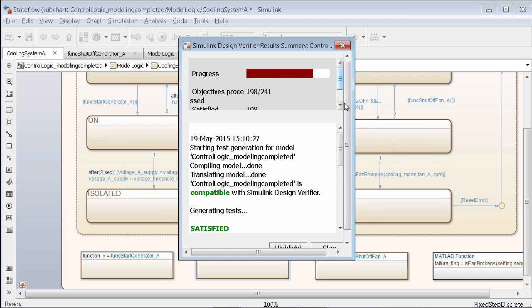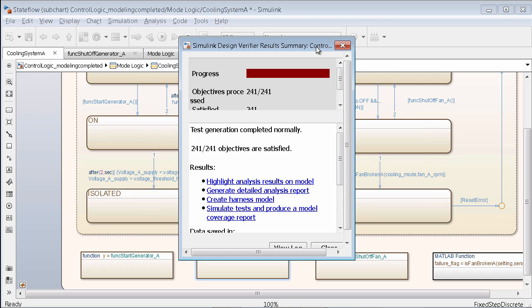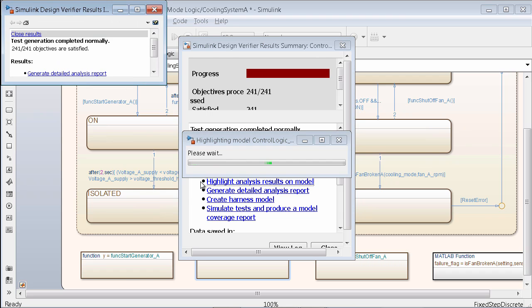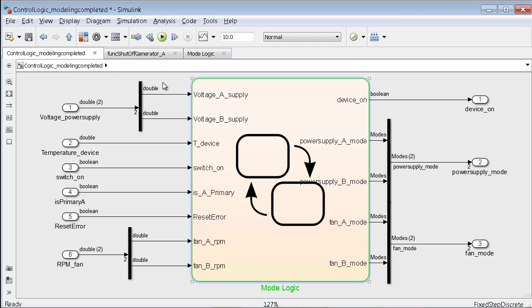Okay. So just to recap, at this point we're not in simulation. Right now, we're using mathematical methods to generate test cases to top off, as you said earlier, the test cases that we had functionally created. Now a user would probably go back and reuse these test cases in simulation and see how it behaves. And if you change your model, you want to reuse the test cases over the model, and run it on software as well, perhaps in software-in-the-loop mode, processor-in-the-loop mode if you need, and so on and so forth. Absolutely. All these test cases are simulatable, and it's adding value to model verification. You're still in the model, you've not yet generated code.